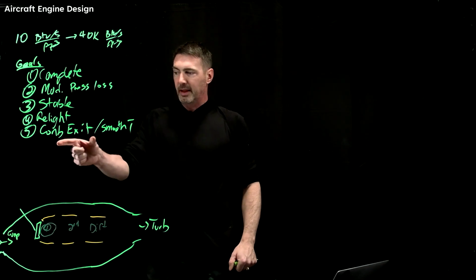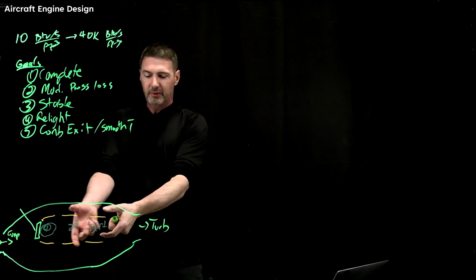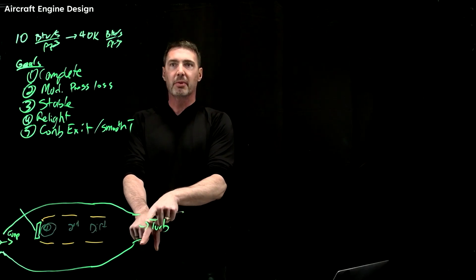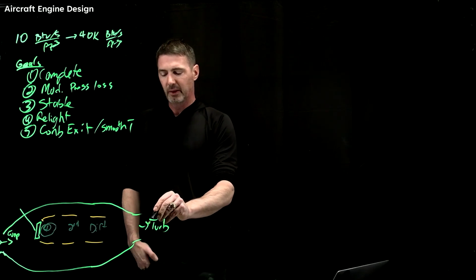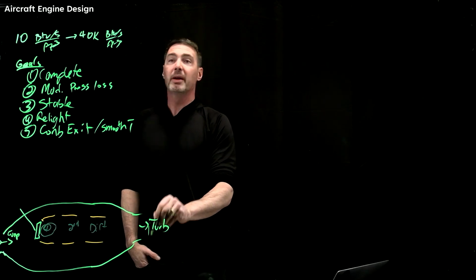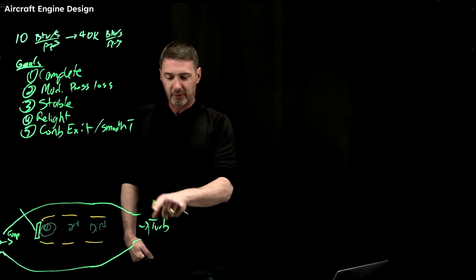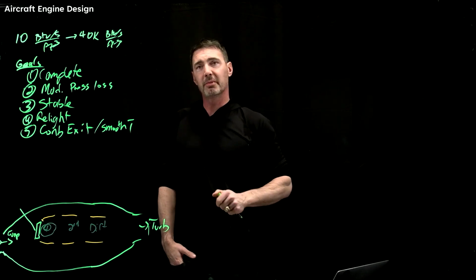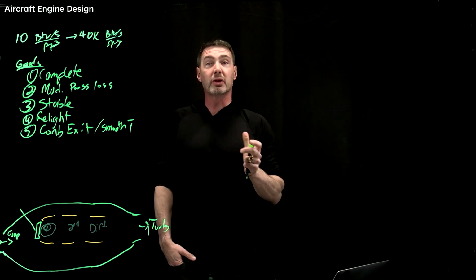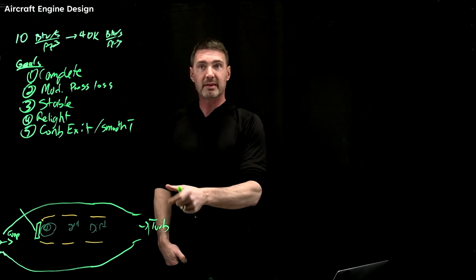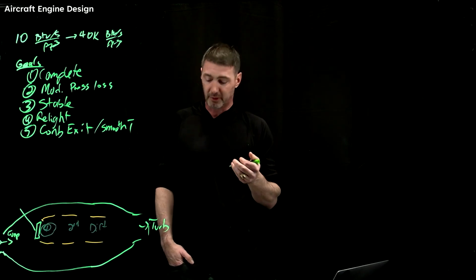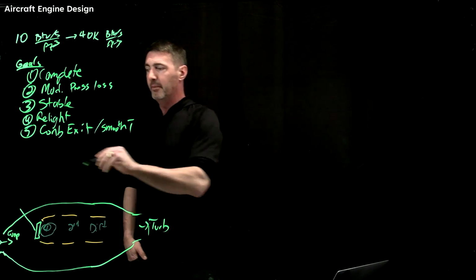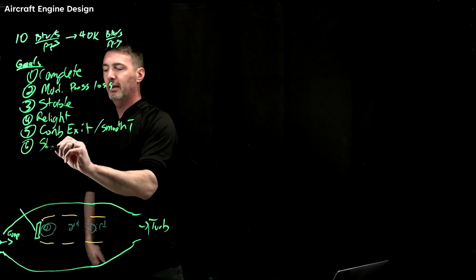And so a couple of things. Combustor exit temperature. That's after you've done all of this stuff. You really want this to be pretty smooth. No hot streaks. Because again, the temperature here is going to be above the melting temperature of this turbine. That's why the intercooling of that first stage turbine was a really exciting research project. A lot of things to do here to improve the performance, both from a pressure drop, but also heat transfer side of things.